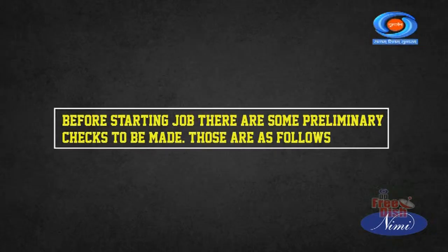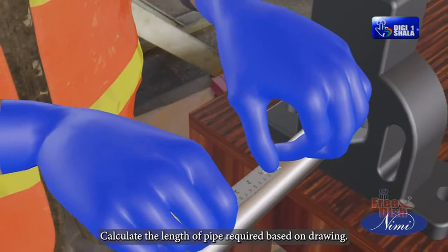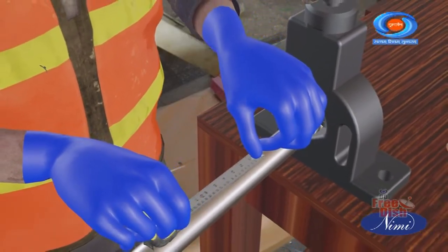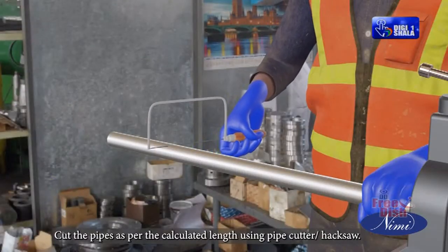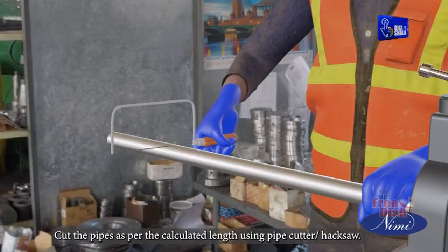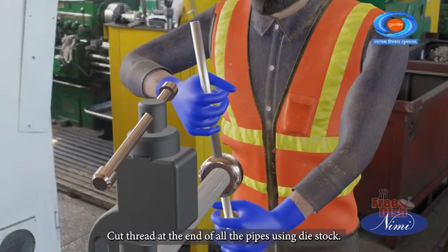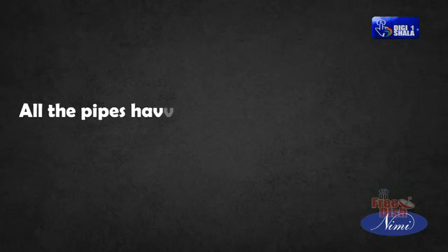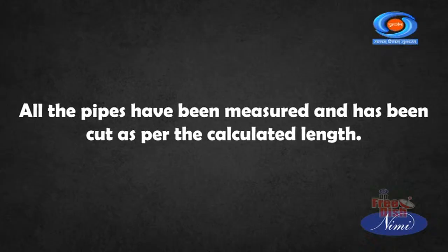Before starting the job, there are some preliminary checks to be made. Those are as follows. Calculate the length of pipe required based on the drawing. Cut the pipes as per the calculated length using a pipe cutter or hacksaw. Cut thread at the end of all the pipes using a die stock. All the pipes have been measured and cut as per the calculated length.